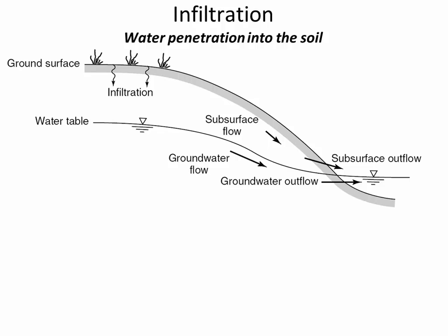table becomes elevated, and because the water table is higher here than it is there, and on the right side of the screen, the water table is only as high as this is a river or a pond. So the water table is going to match the elevation of this pond or river. And so there's sideways movement of the groundwater because of the gradient in the water table.